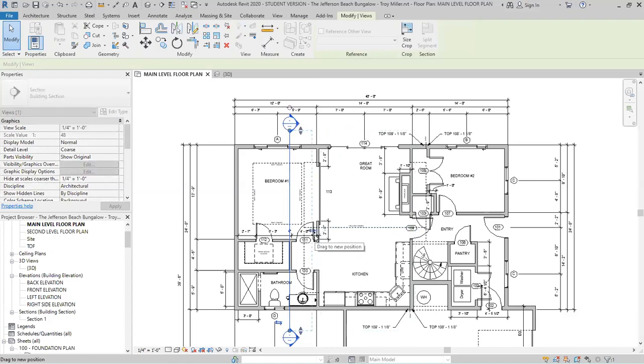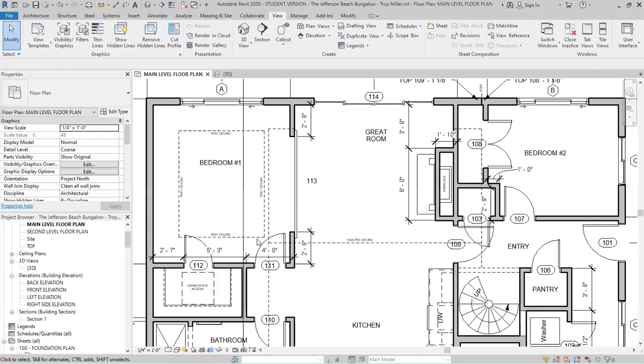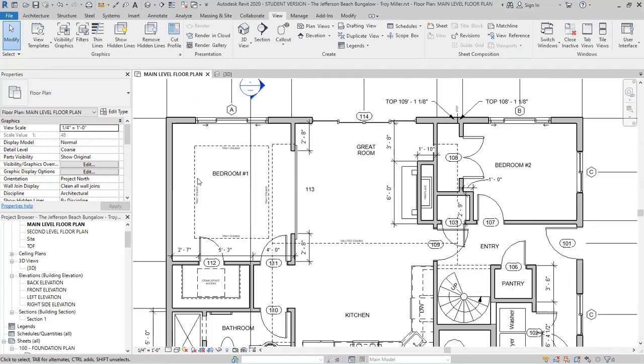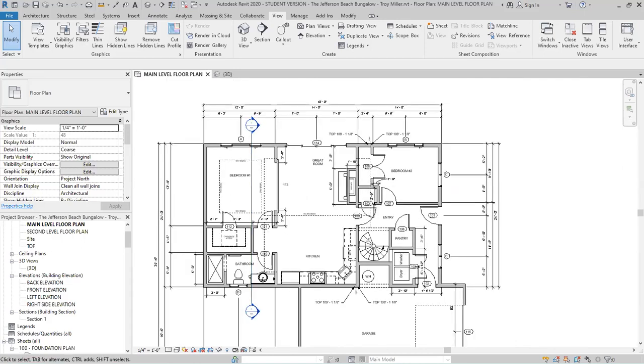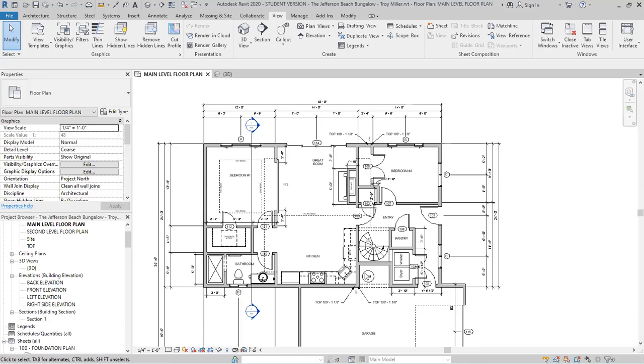I'm actually going to take it back to this point, because if I were doing this in a real set of drawings, with the placement of this building section, I'm really interested more in what's happening to this wall. And if we take a look at what we have here, we've got another building section coming through here that would show us the fireplace and that part of the kitchen. So there's no reason to do a view depth that exceeds the depth of another vertical cutting plane.